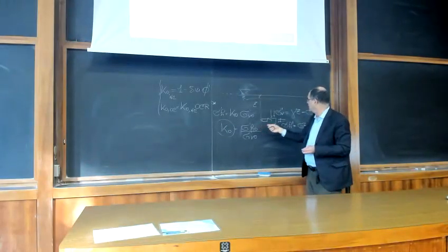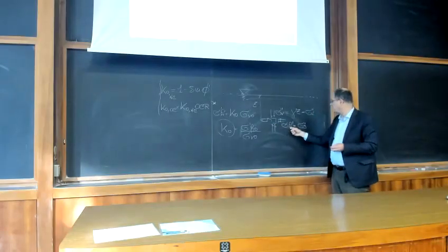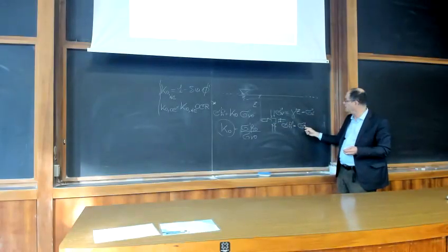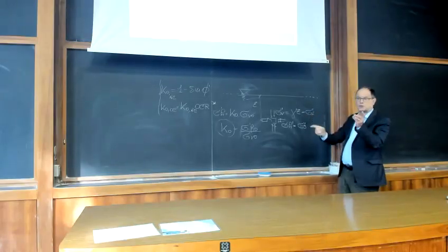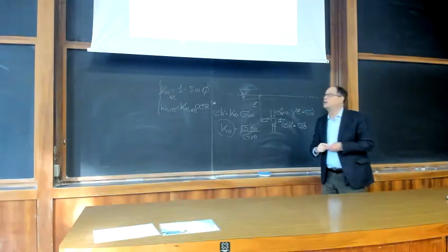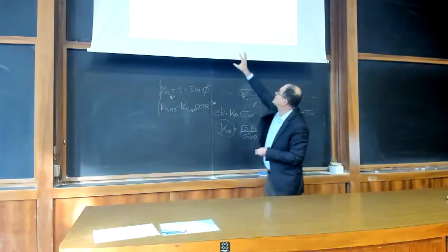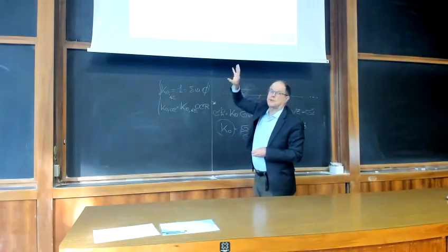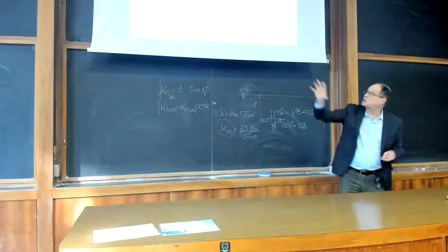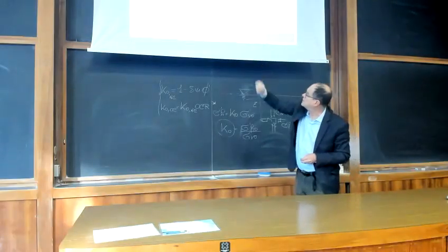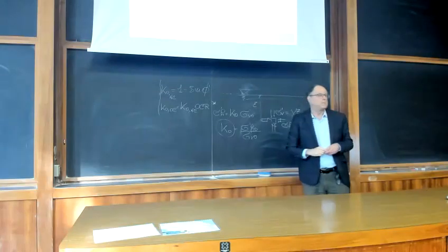In this case the horizontal stress would become sigma 1, and the vertical stress becomes sigma 3. So you have an inversion of the principal stresses. But still, the initial stress state is represented by a Mohr circle, like in the left-hand side picture.